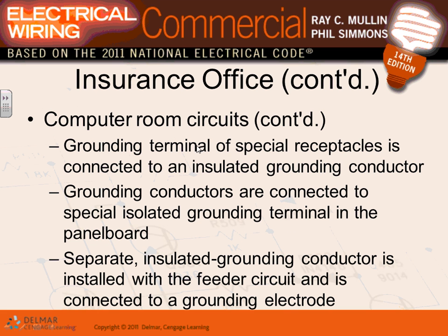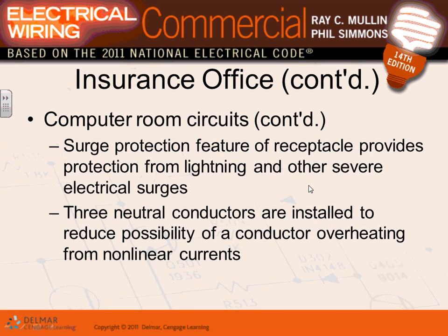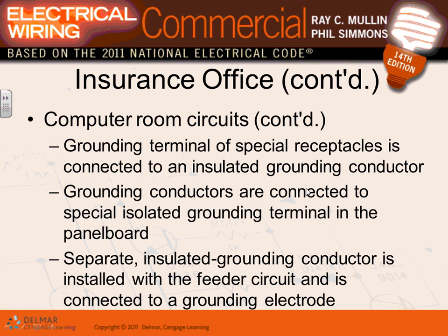For an isolated ground receptacle, guys, the receptacle's ground slot is completely isolated from the yoke. That's what an isolated ground receptacle is. It is connected to the grounding slot with an insulated conductor that takes you all the way to the panel. Who cares? When you have an isolated ground receptacle and an insulated grounding conductor, it will minimize interference with your electronic equipment. That's what you're trying to do.